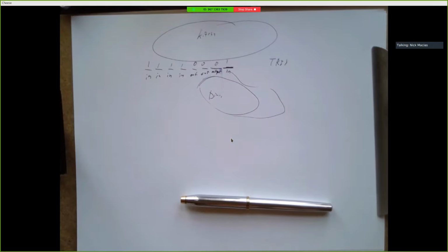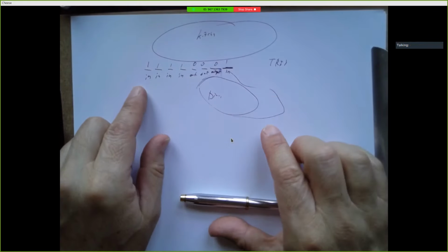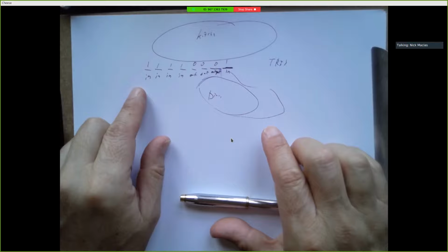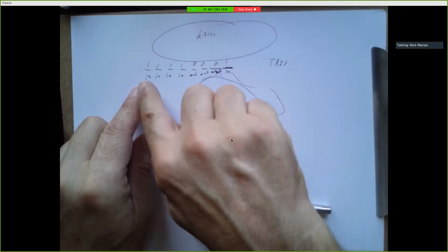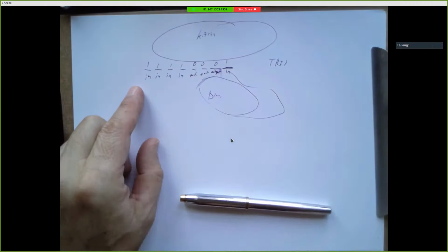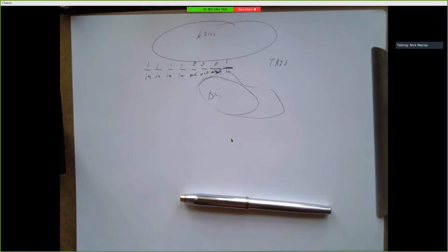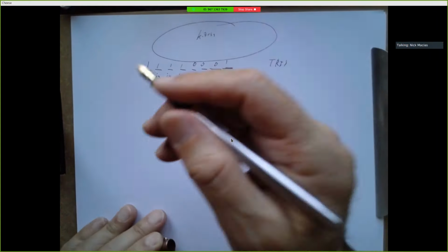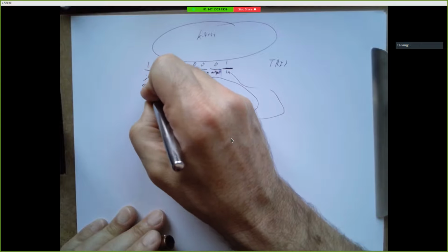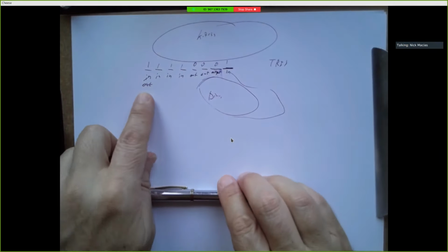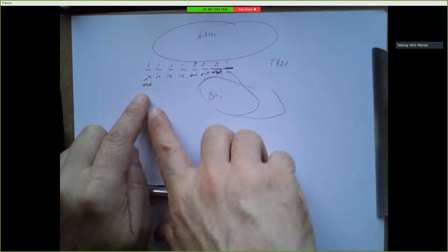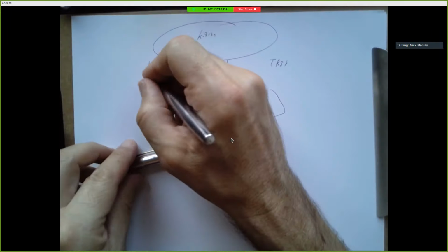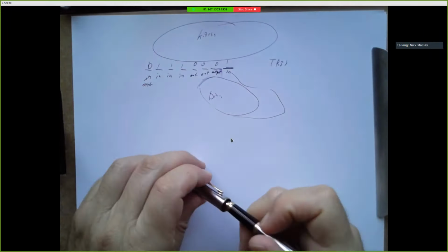The other takeaway is that unlike in real life where we could have 8 signs, for some reason in this restaurant you have a single sign with 8 things written on it. And you have to hang that 1 sign above all 8 doors with in and out written on them. So if I decide, for example, that I want to change this to be an output, in general I can't just say set tris to be a 0 over here, right? I need to specify all 8 bits.